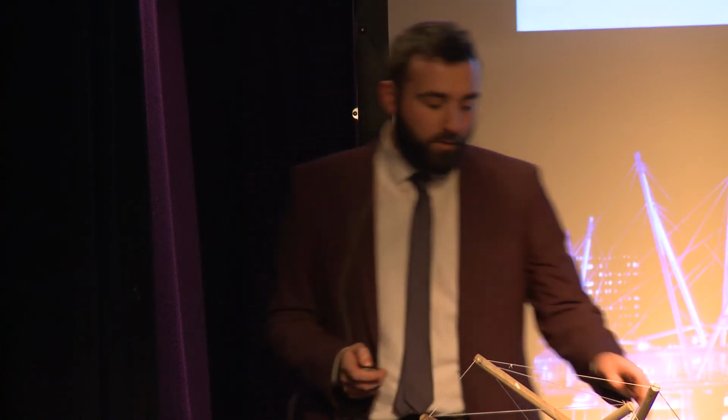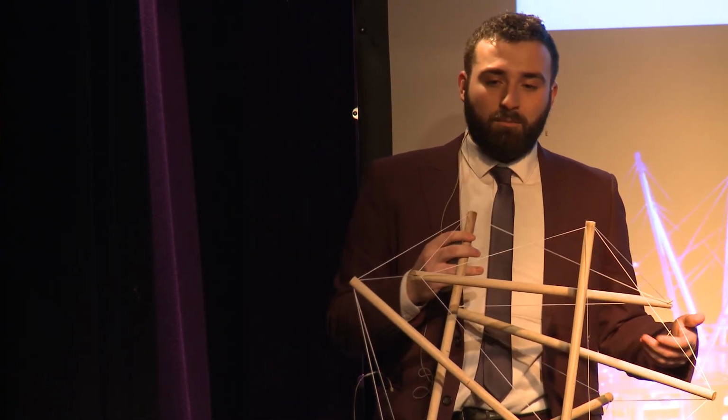Two things. One, cost, and how do you make sure it doesn't blow away? Well, on the blow away question, there aren't strict rules over tensegrity, so you can have a strict tensegrity system, which is one like this, where it stands by itself. But then you can have unstrict tensegrity systems, the likes of the bridge you can see there. It has other supports because it's more practical. I think you're cheating. Well, it's still different. And on cost, the big cost would be in the fibres, where you have to get the material selection right so that if you cut one, it won't fall apart. But the main thing with cost is it can actually be cost efficient because of the way it spreads loads throughout it. It can be an efficient way of design because you can design it to have fewer members, because the load is dissipated through the whole structure.